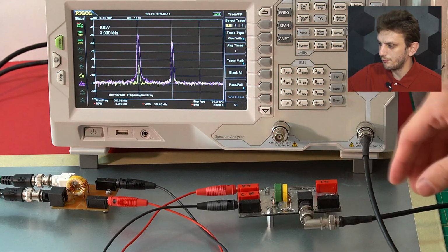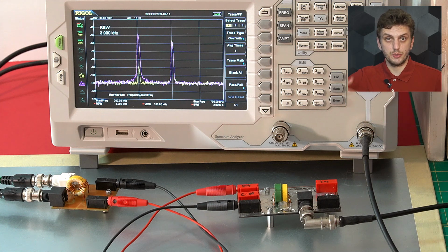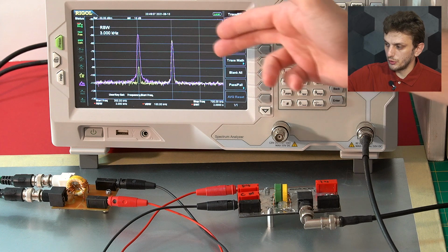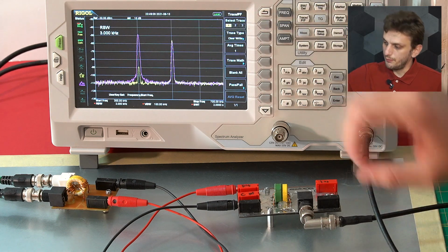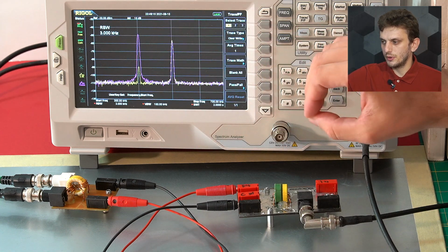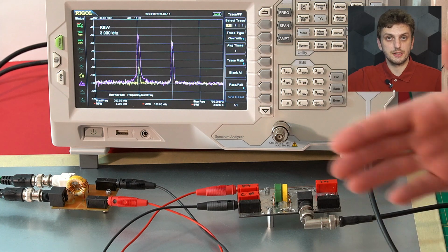Now if we connect it to our separator board, first of all, if we insert the signal into our differential mode input, we can see that our right spike is almost exactly the same as what we measured with our LISN. So we can clearly see our differential mode noise being unaffected by the separator, but our common mode noise is about 40 decibels lower than our initial measurement. So this is a 10 decibel per division scale.